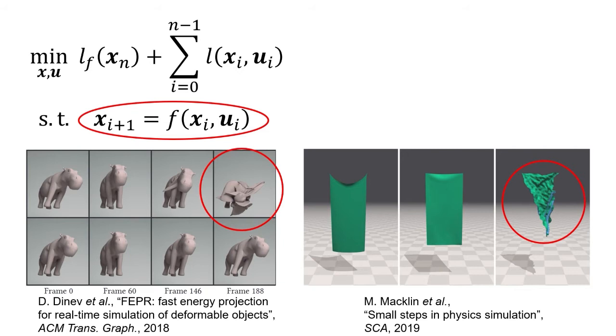This has been verified by several independent works over the last few years and has been confirmed by our own experiments as well. These issues make explicit integration unviable for simulation and control of soft objects, as they fail to reliably predict motions. Therefore, in our experience, these systems can only be stably handled by applying implicit integration schemes.